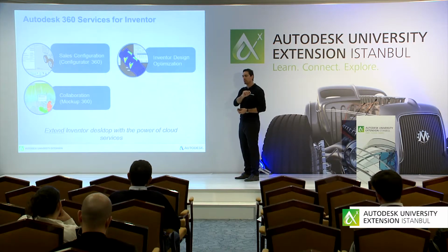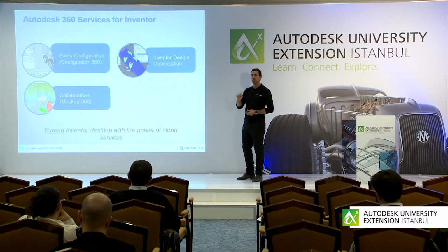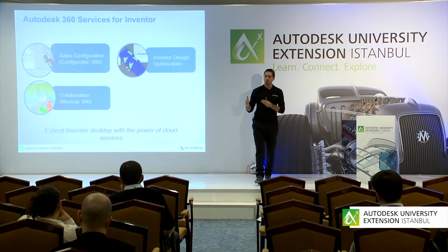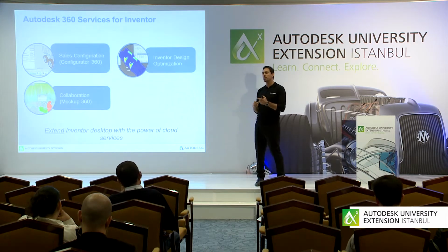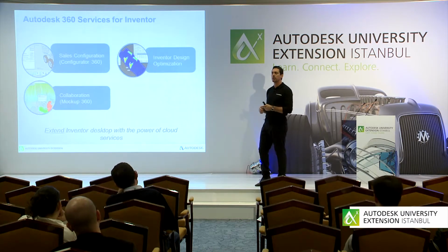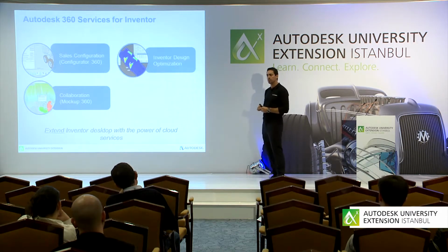So I can set up a thickness of 12 mm, 10 mm, 14 mm, 15 mm, and I can set up 3 different lengths. I can send this to the cloud. It'll come back and notify me that your 10 mm with a 300 mm length is your optimal design according to the safety factor you've set out based on that force or that load.